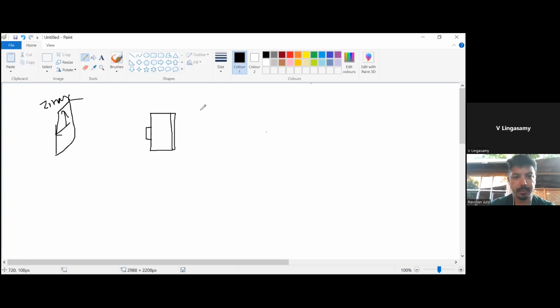Next, you can have another port here also. For example, if you have a frequency selective surface or transmitarray unit cell, no problem, you can have another port here, Z min. In terms of S parameters, this is port number one and this is port number two.